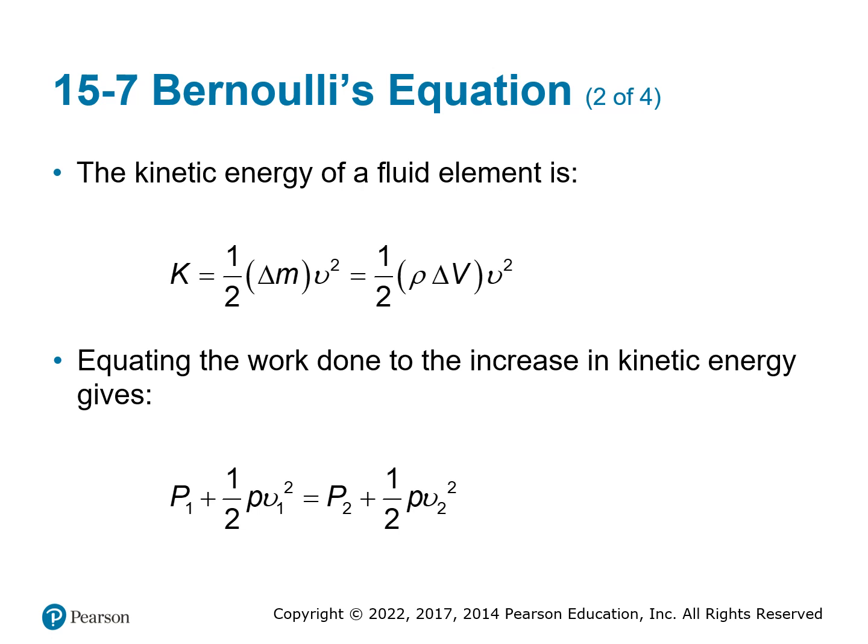If you set that equal to the work done, because if there's work being done, you have a change in kinetic energy, you can say that the pressure plus the 1/2 times density times velocity squared is equal to the pressure of the second point plus 1/2 times density times velocity squared.